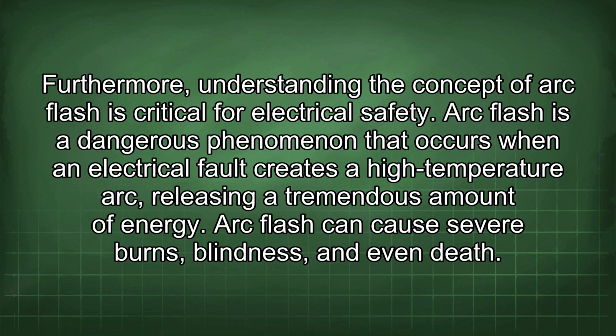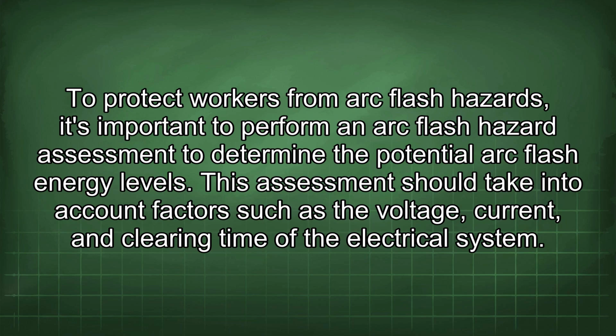Furthermore, understanding the concept of arc flash is critical for electrical safety. Arc flash is a dangerous phenomenon that occurs when an electrical fault creates a high-temperature arc, releasing a tremendous amount of energy. Arc flash can cause severe burns, blindness, and even death. To protect workers from arc flash hazards, it's important to perform an arc flash hazard assessment to determine the potential arc flash energy levels. This assessment should take into account factors such as the voltage, current, and clearing time of the electrical system.